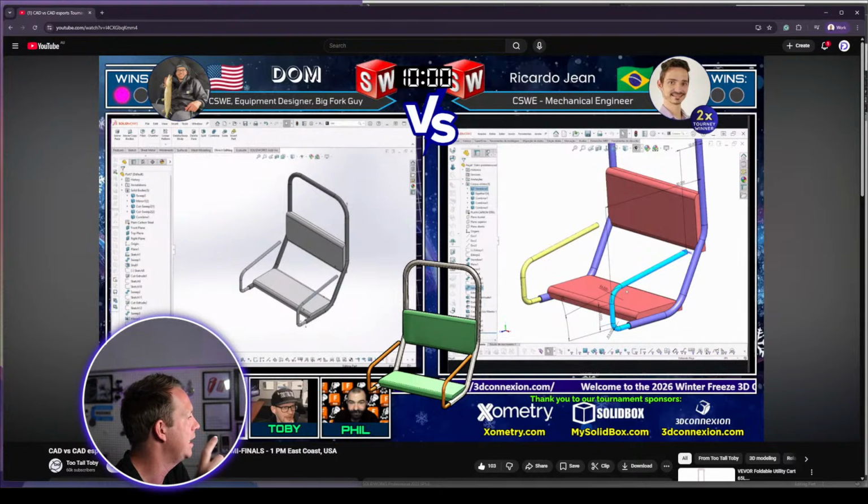Where I was saying in the chat here on this one, this is where you need to use a sweep cut, because any more than 1 indent at a time, sweep cut can do as many as you need in one go. All right, and that's what Dom's got. So Dom the Pro here, cut sweep. He's nailed it with that feature down here.